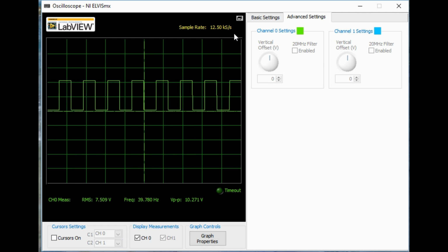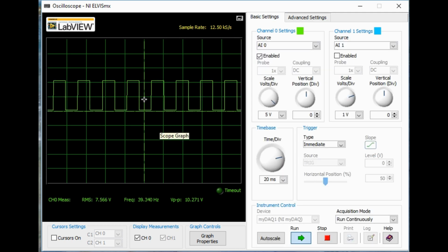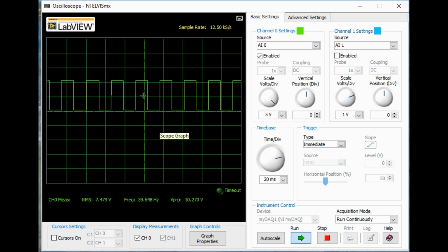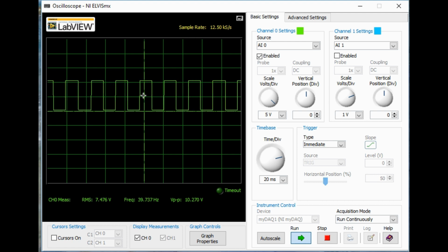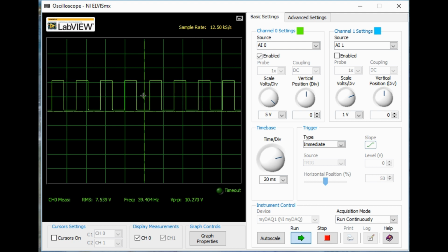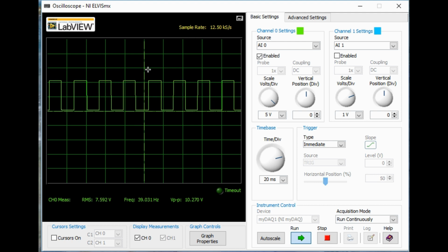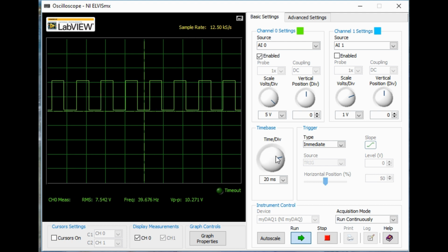But just so we can see some of the type of waveforms that we've got going on here, let's have a look. So this is the drive to the buzzer at the moment, or what the Tesla coil will be driving. That's coming straight from the high side driver. So you can see that's the gate charge there, the gate voltage there. We're getting about 10 or 11 volts. This will be one diode drop below VCC because of our bootstrap diode. So that's important to remember.